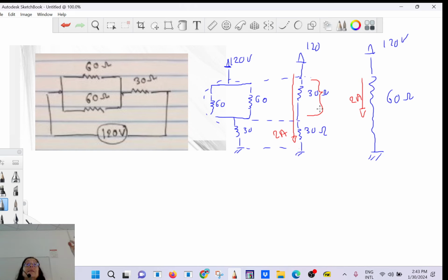So it's going to be the voltage drop is Ohm's law. 60, right? And this one is going to be 60. So one more step back. So this is 60 volts, and that's going to be 60 volts, okay? Because it's the same height. This is high, this is the base. So where is my current? I forgot to draw the current here. This is 2 amps. 2 amps was here. So this is 2 amps here. Has to be 2 amps coming back to base.